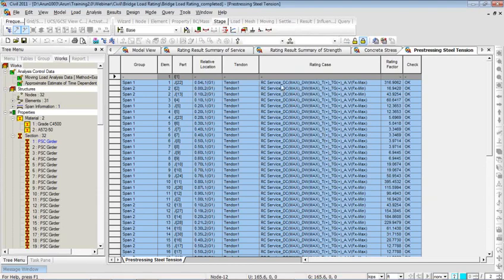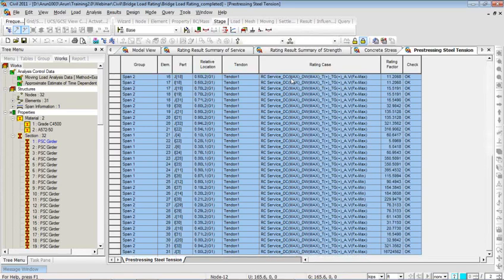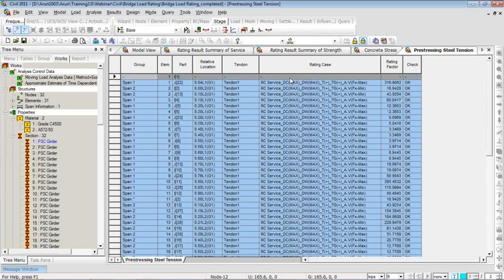So the best part is when defining the rating case, the program clearly gives you which cases are being compared. So DC max, DW max, T plus, TG plus. So basically DC is the type of load case, and the max means the value that you enter in the two columns for maximum and minimum. So the program takes into account the combinations from there. So all the combinations are shown here, and under all combinations we are getting okay results.